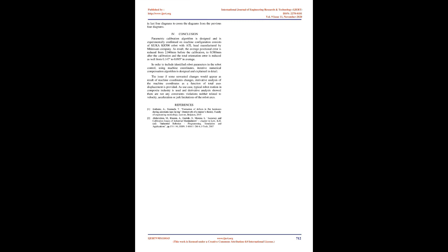Controlling the robot motion by sending the machine coordinates to the robot controller, the focus of interest is moved to the machine space. In the case of the 6R industrial robot used in this research, it is a 6D machine space. Between any two successive points in the G-code, the tool always should travel a 5 mm displacement. In general, every robot axis should perform a different displacement, if any. As a consequence, velocities of the robot axes are different at different points in time. In this case, trajectory planning is left to the controller, and it applies its own algorithms to interpolate several values, taking into account not to violate the machine configuration dynamics.